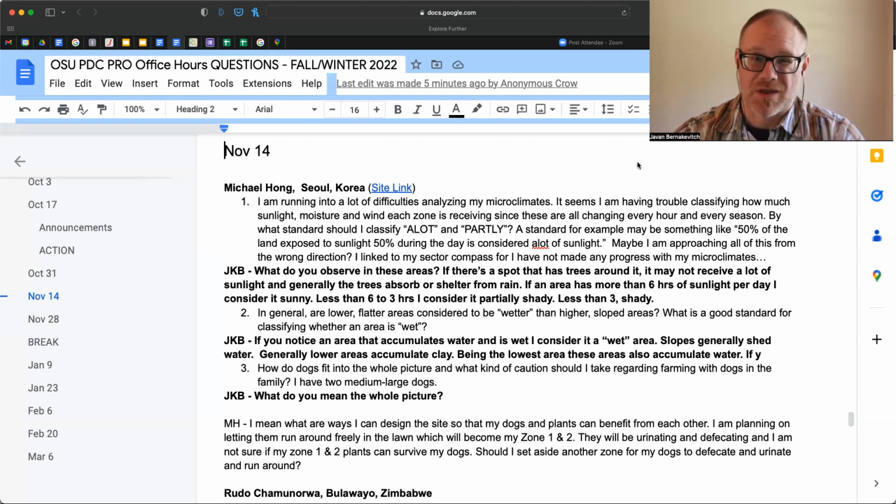You can do the same thing with a number of programs. These are mostly vector-based landscape programs. Things like Vectorworks or Landscape Architect does this as well. But you can also just do this all by taking the heights of different elements within your landscape, and then getting what's called the shadow ratio or the shadow angle, or just calculating the shadow. And so basically, if we have, it's the height divided by tan, or the angle of the sun during that period of time.